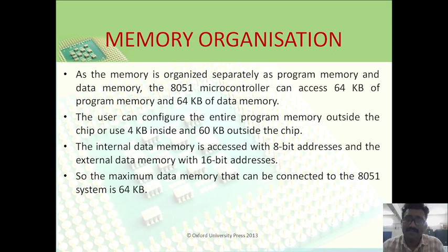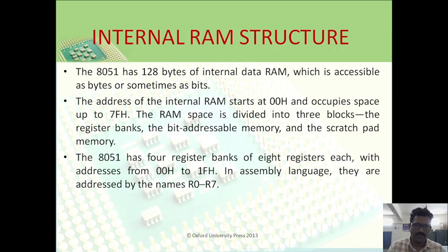The user can configure the entire program memory outside the chip, or use 4 KB inside and 60 KB outside the chip, no problem. The internal data memory is accessed with 8-bit addresses and the external data memory with 16-bit addresses. So the maximum data memory that can be connected to the 8051 system is 64 kilobytes.